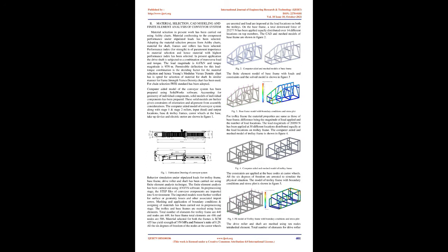When the feed conveyor is loaded with tomatoes, first stage sorting occurs at this instant itself. The pitch of rollers on the first stage feeder is 38 mm, hence tomatoes of diameter smaller than 38 mm pass through this gap and are collected at the bottom. The tomatoes of larger diameter that remain on the conveyor during the first stage are carried upward for second stage sorting. The roller pitch in the second stage is 47 mm, and hence tomatoes with size of 47 mm or larger will be sorted for further packing and tomatoes of smaller size are collected in the tray attached to the trolley frame.